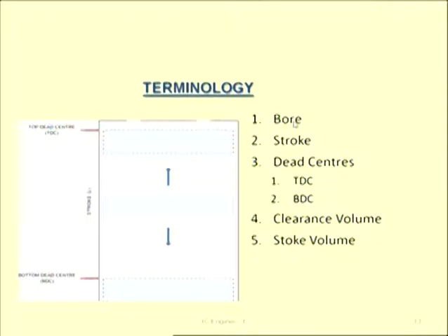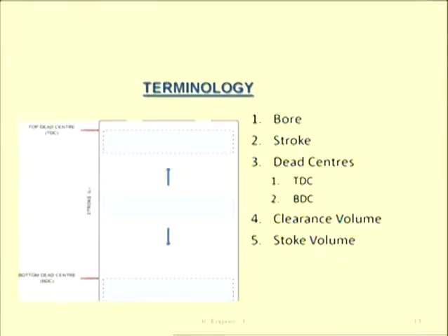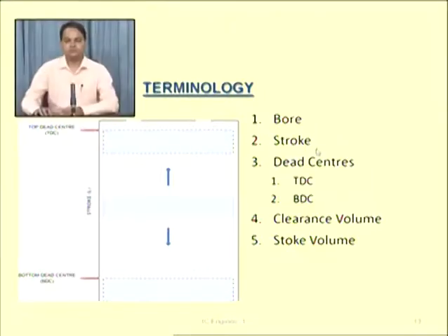Normally in engines we ask what the cc of the engine is. CC is nothing but the volume inside your cylinder, in cubic centimeters. So centimeter cube, the short form is cc. When we say cc engine, it is a volume, and as it is cylindrical, you can calculate using an equation, and the diameter you can get. So whatever diameter you get, that is called the bore.